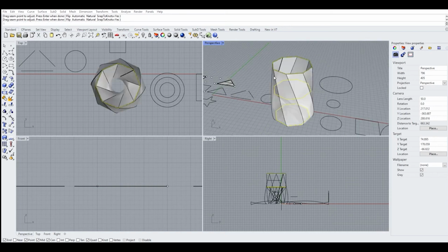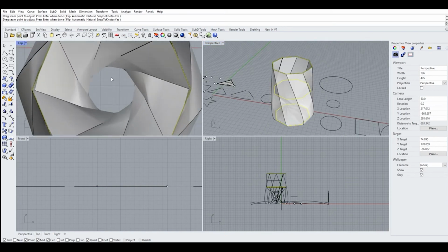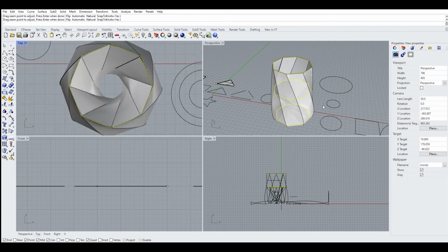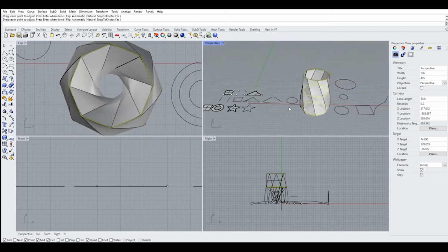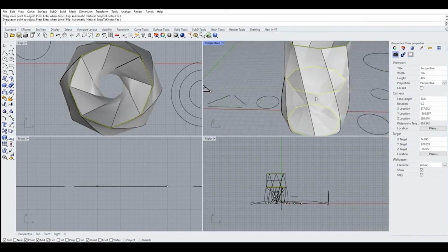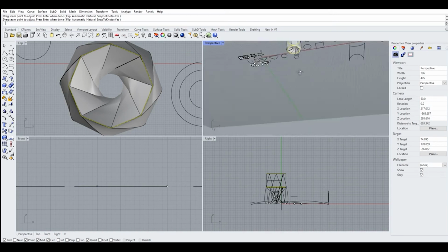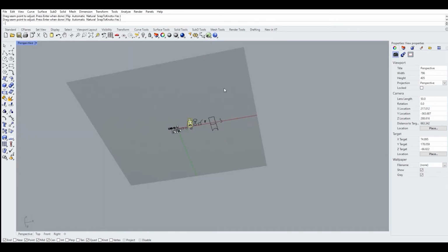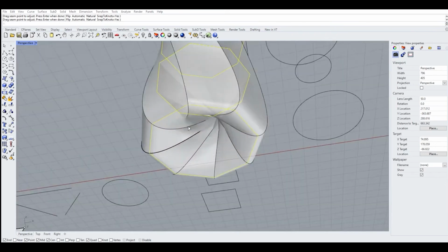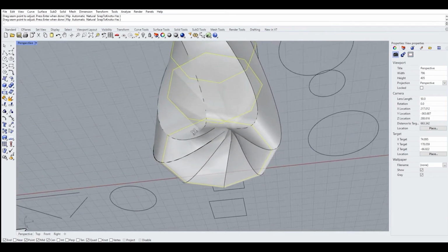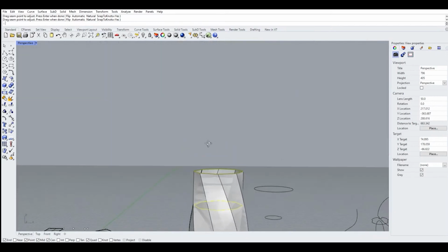And it creates this very weird folding in on itself shape. Now that shape, as you can see there, it looks like it's folding in on itself. That shape wouldn't be possible in the real world. It's folding in on itself. That we call a self-intersecting surface. Two surfaces occupy the same space at the same time, and those shapes aren't reproducible. As an illustration, I'm going to maximize this window quickly, and I'll show you. You see how it flows in on itself there. That is very problematic.